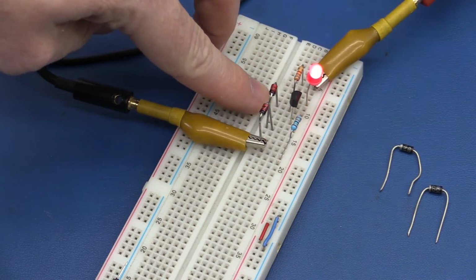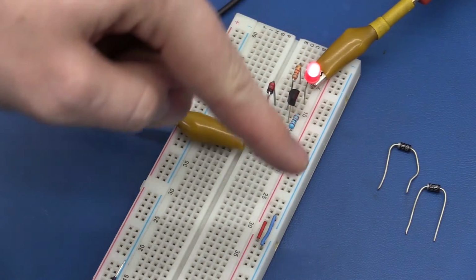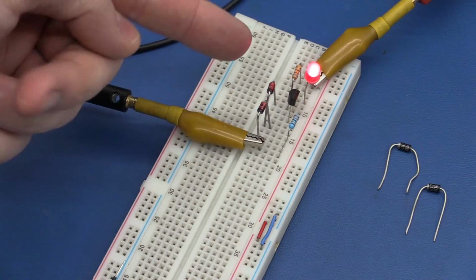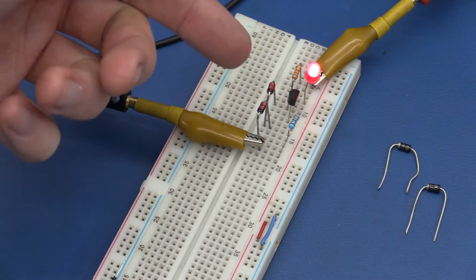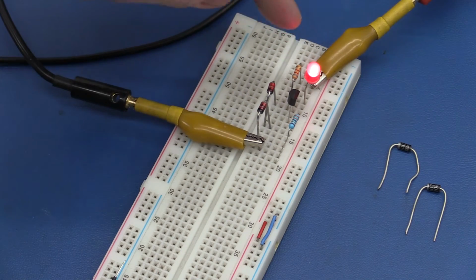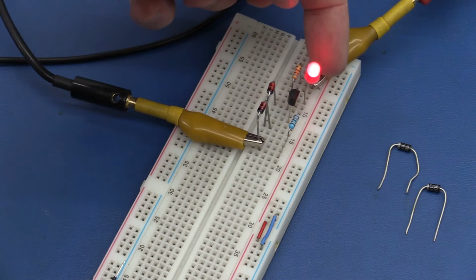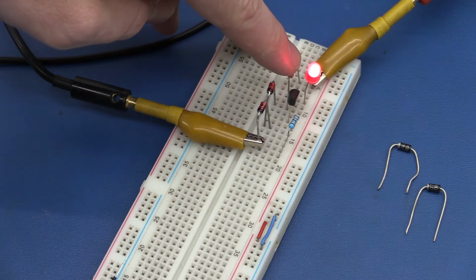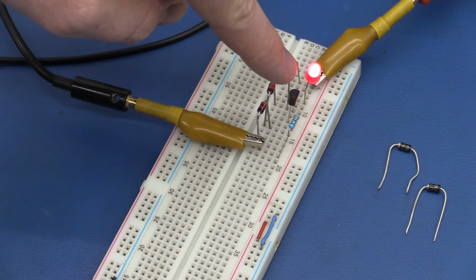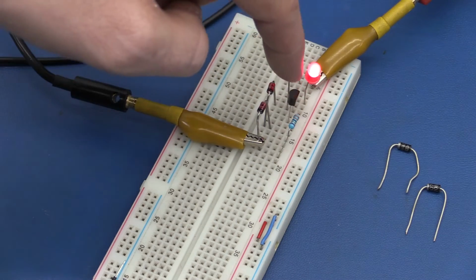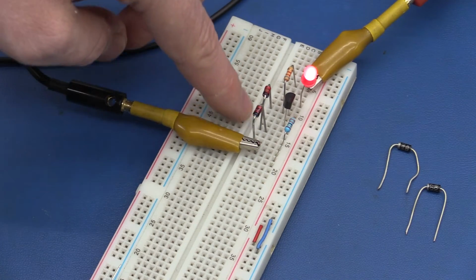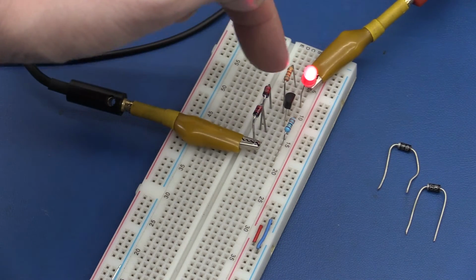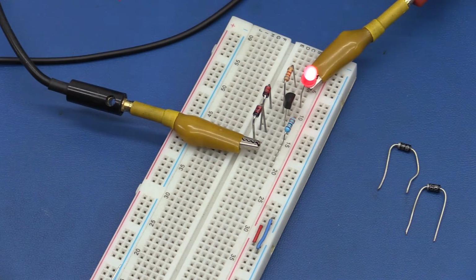If the voltage at this point is not the same, then the current will not be the same. And that's the disadvantage of using diodes, is that when the current changes, the voltage will change also. And the current does change when we apply more voltage from the supply, because we get more current through this resistor, and all the excess current that doesn't go through the transistor will be burned off in the diodes. So that increases the voltage and increases the amount of current that can go through the transistor.